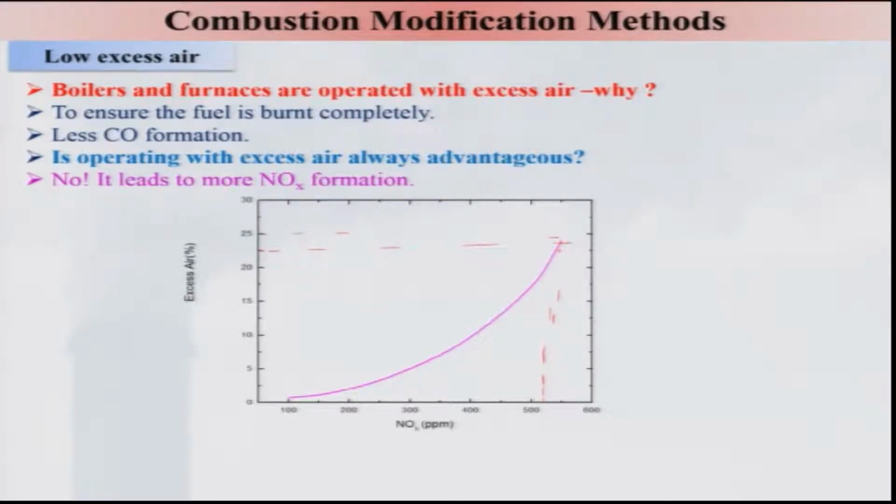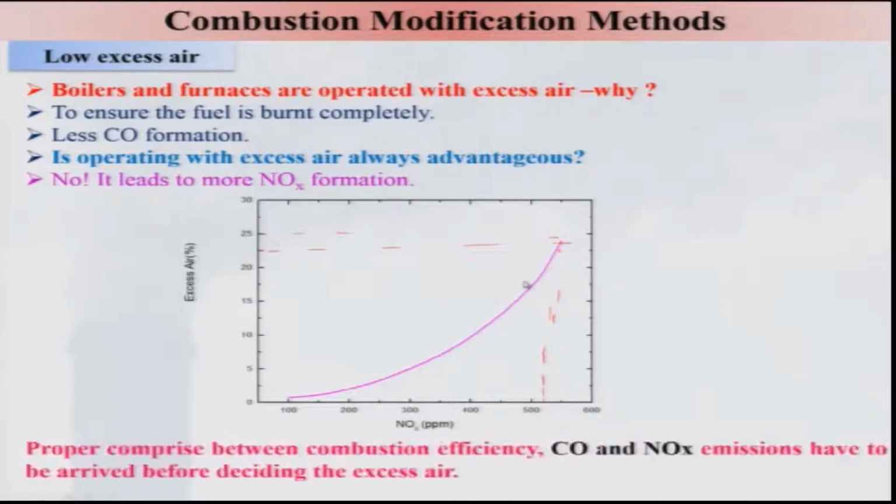But what we need is that we will have to make a concerted effort to optimize the excess air, such that we will have a reasonable amount of CO formation and also a reasonable combustion efficiency, with a reduction of NOx emission. So, that we will have to keep in mind.